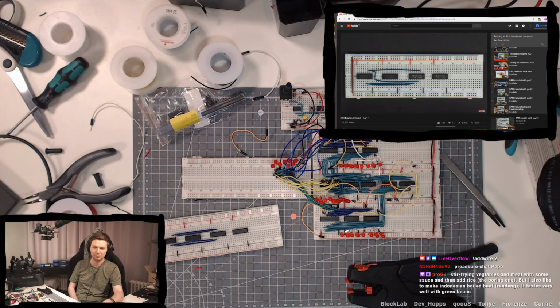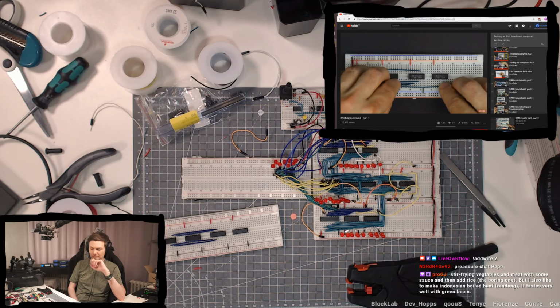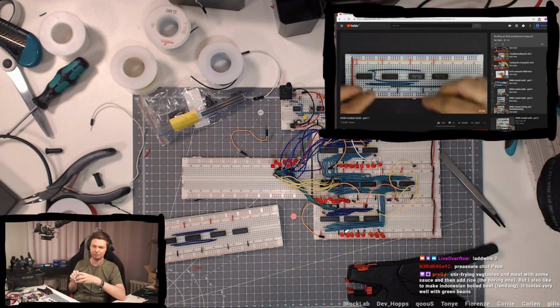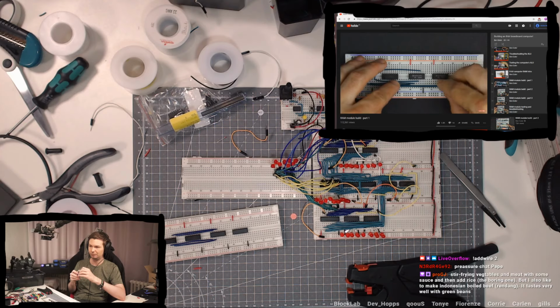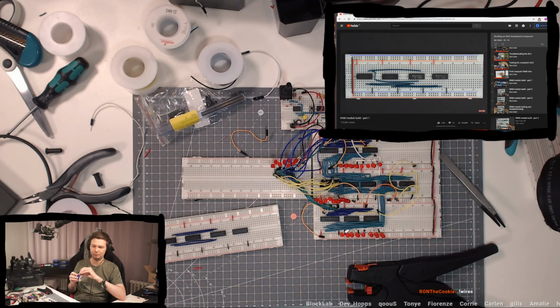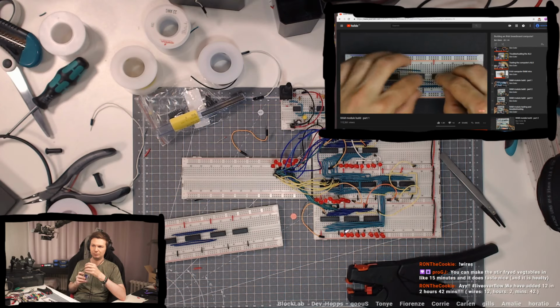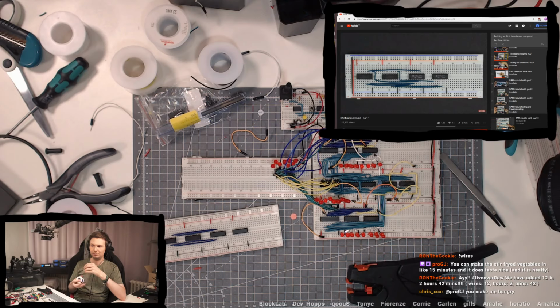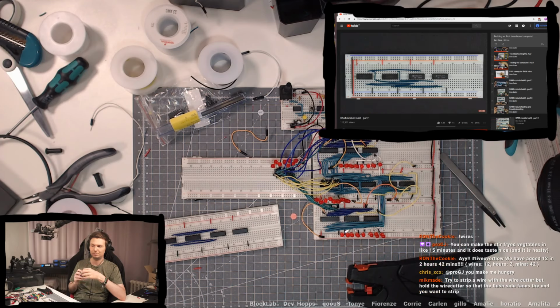I saw a few people commented on the last video asking why use the 74LS189 when you have to hook these inverters up to it, which seems a little inconvenient. Yes, it is a little inconvenient, though not terrible. I looked and there was a 74LS219, but I couldn't find it anywhere. If you get your hands on one, it doesn't require the inverters. There are other chips too. I didn't do a ton of research to find the absolute best chip; I'm just using what I've got available. If you want to find a different chip and use that in yours, I definitely encourage you to do that.